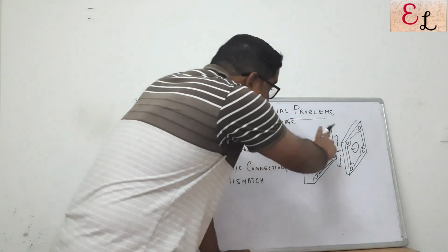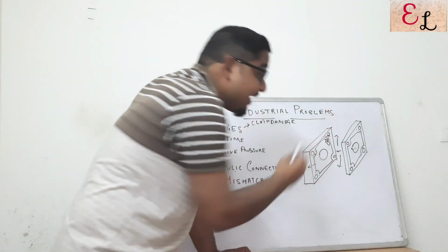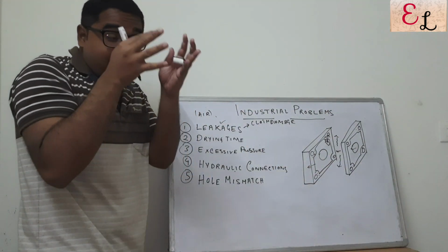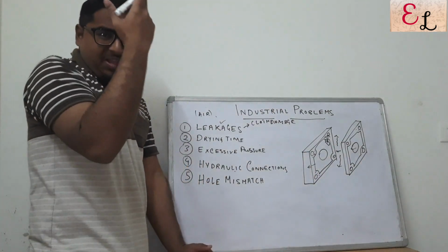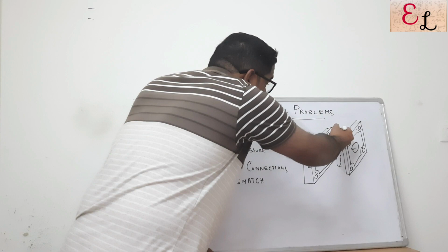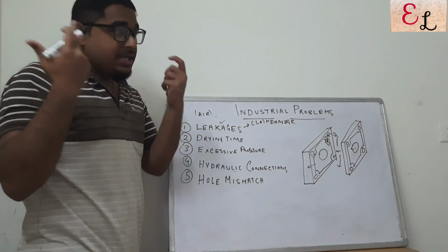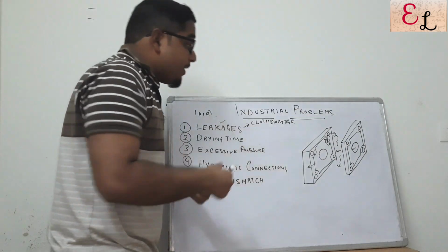There is no solid deposition on the filter press cloth, because the liquid is finding a path of less resistance, finding a tear or a cut or a hole, and passes through the cloth and moves into the drain hole to go through the outlet. So whatever is incoming is outgoing, and no separation of solids is taking place at all, because the filter press